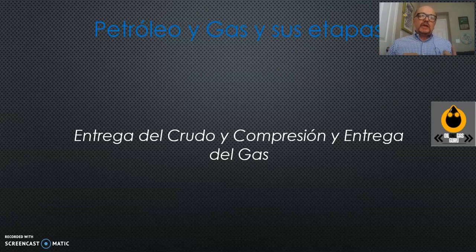And I wanted to tell you also about the optimization of the gathering of the fluids in the field. If you have a gas lift well, you do it by optimizing how much gas or how much compression capacity you're going to use in the well, depending on the nodal analysis of the reservoir, the capacity of the reservoir to put fluids in the well, and the transportation curve. The well changes if the gas lift is being optimized. And when you have a pump, like I mentioned, the optimization is because of the energy needed for the new well, which is producing less oil, and we shouldn't spend too much electricity on it. So that's what we call optimization of the whole field.